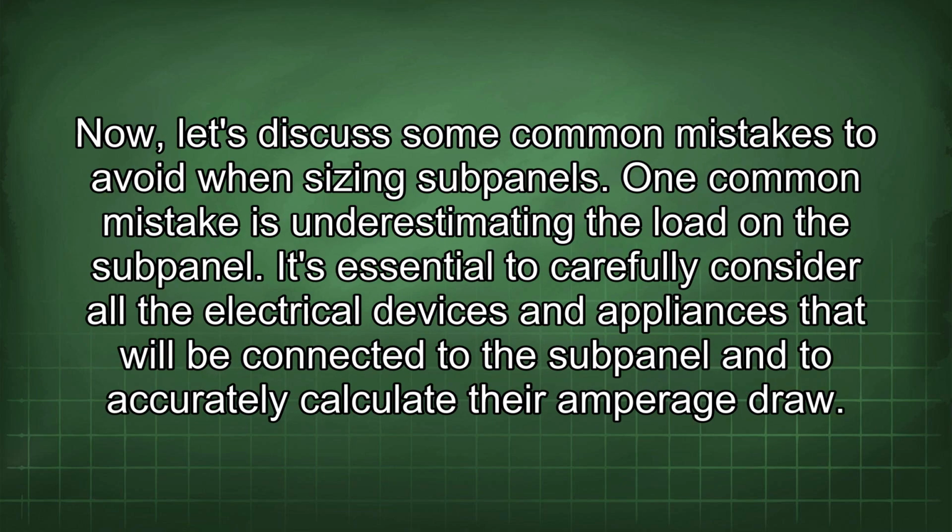Now, let's discuss some common mistakes to avoid when sizing subpanels. One common mistake is underestimating the load in the subpanel. It's essential to carefully consider all the electrical devices and appliances that will be connected to the subpanel and to accurately calculate their amperage draw.